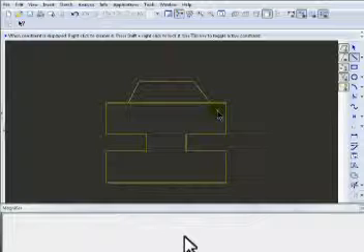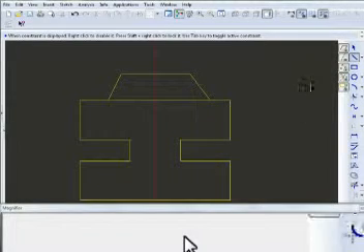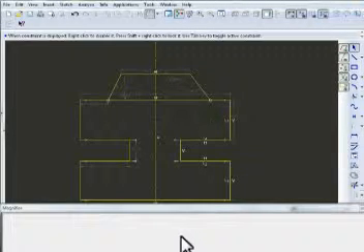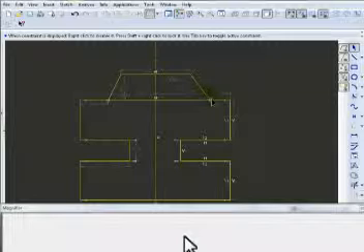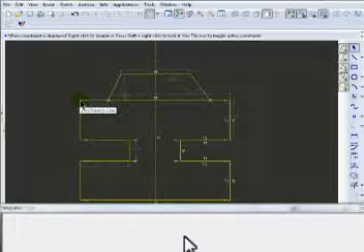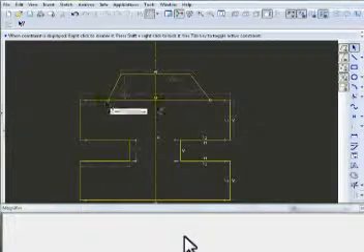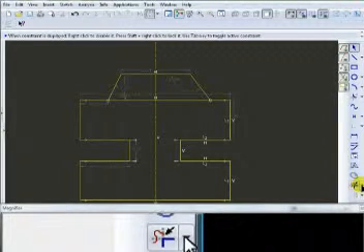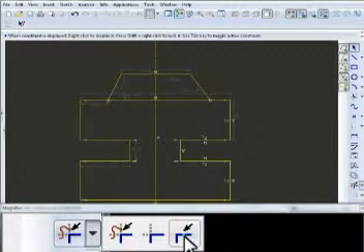And now this tutorial intends to teach you another way of trimming. Now to trim a corner, which means this line, that line, and the corner trim removes anything extended beyond the intersection. But the problem with this, if you do it right now, is it's going to remove this whole line all the way back to here. Well, really, you want to keep this line. So you might want to divide this line in two. And this is the tool to divide it. Select the division, and just click any place there.